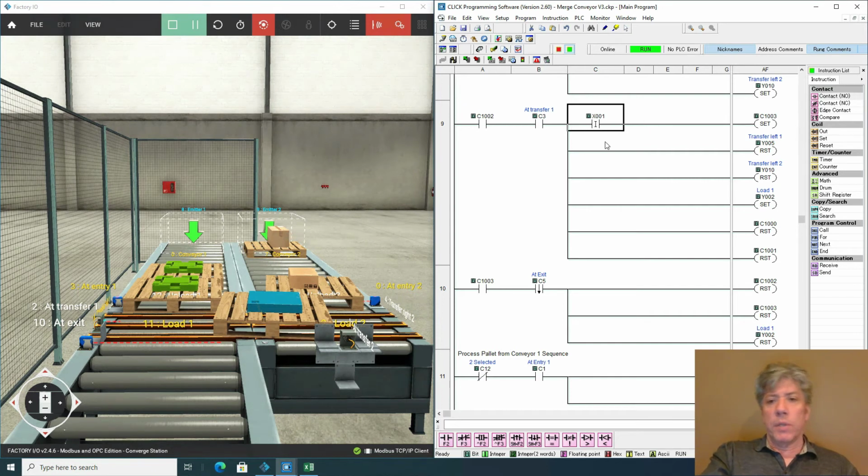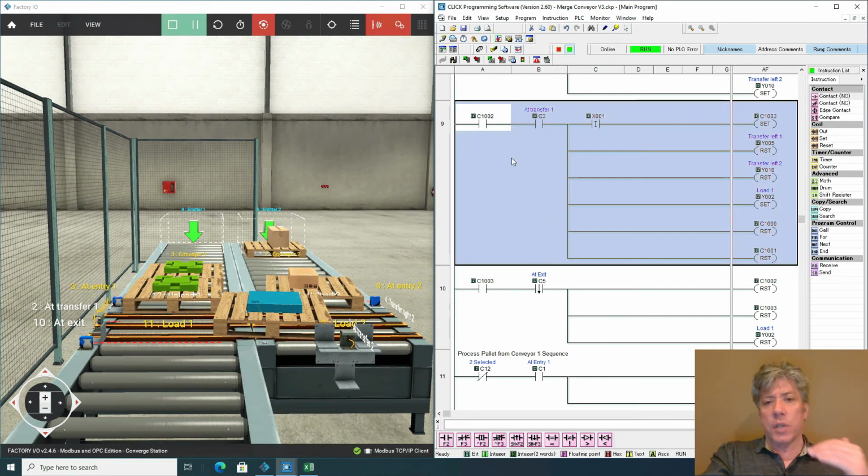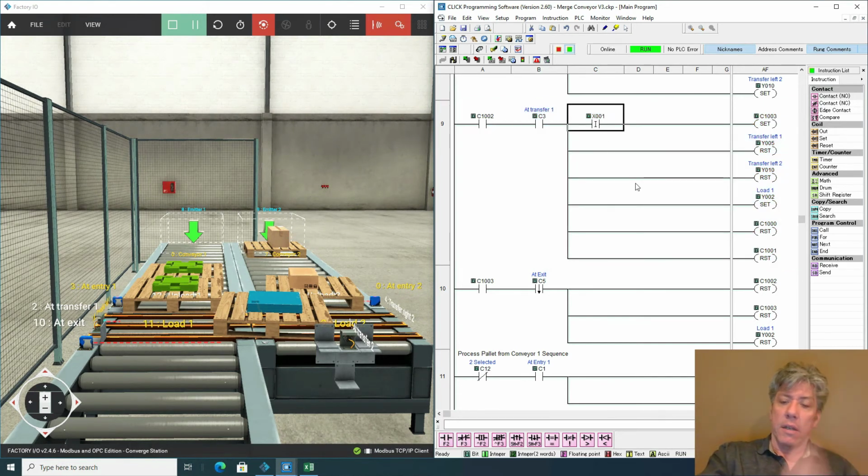And so what the PLC will do is once it gets to this rung, it will actually not really stop, but it'll go out and say, okay, well, you want me to look at this? Okay, I'll go grab that one input and see what it is right now, because maybe it's changed as I've gone through this long program. And if your scan time gets long, immediate addressing can alleviate some problems. But I don't think that's what happened.